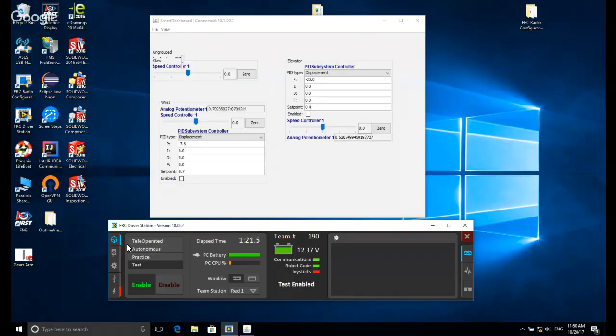There are some that do. Oh, okay. Yeah, so there are two: encoders with an indexing pin, which will let you index on it, and then there are absolute encoders, which are less common, which also let you do that, and which have individual digital values for each position. So watch the video. A lot of that stuff's explained.